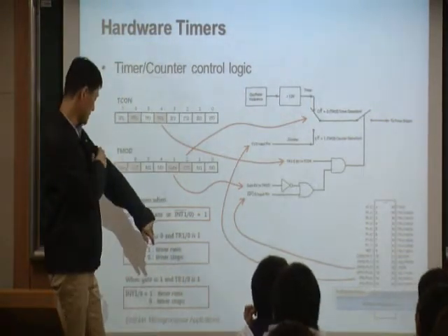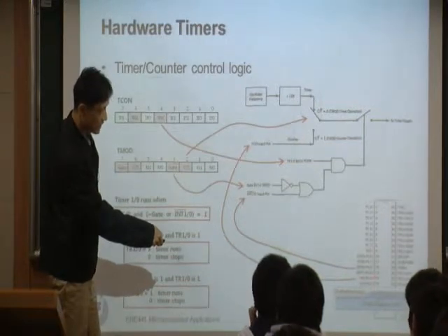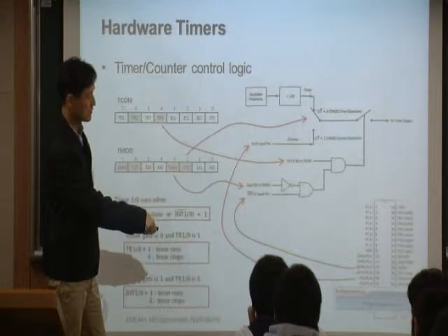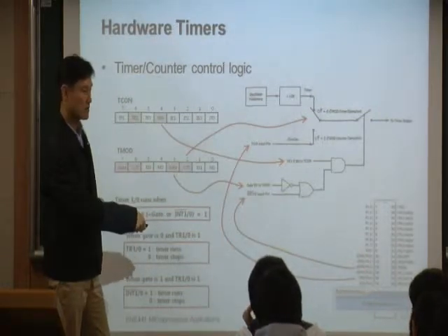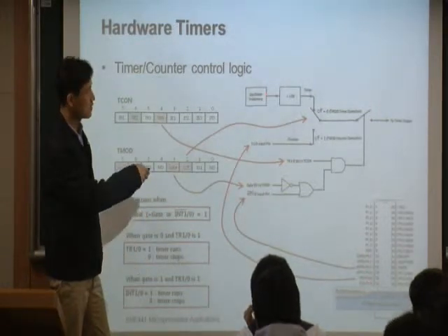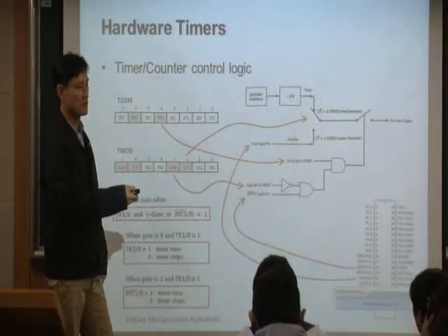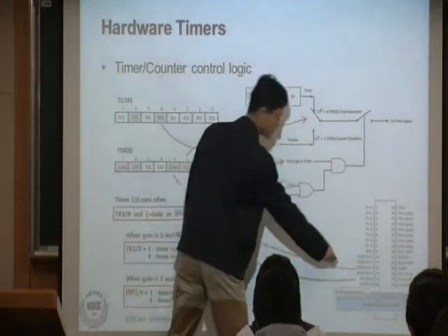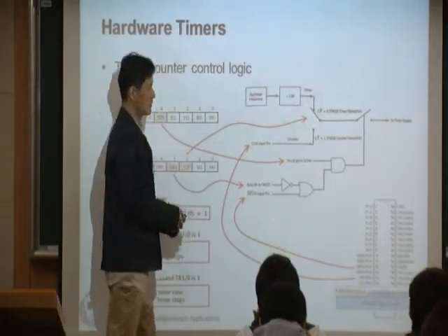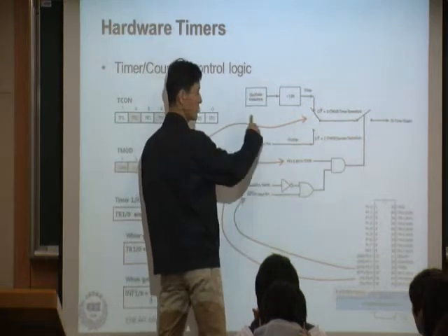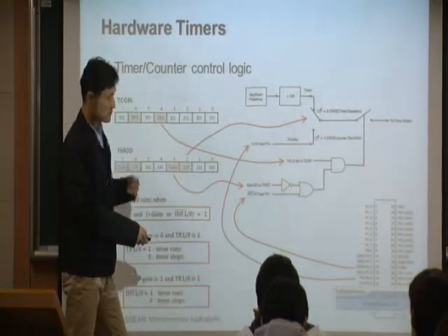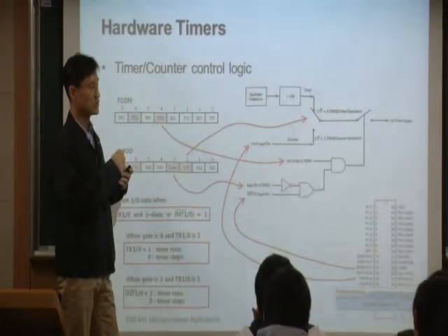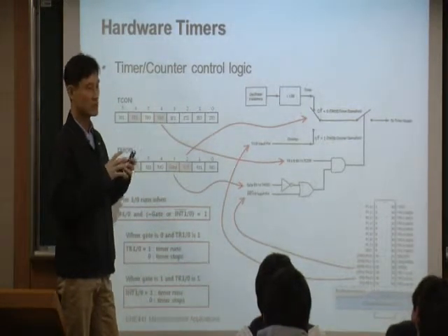What this basically means is that for this particular pin on the 8051, you can now connect some clock right there. Some clock, not this one, but an external clock, whatever clock you want. From the external, you want to connect to here. So in this case, maybe you can connect like this. Suppose that using this pin, maybe you can connect to your own hardware.